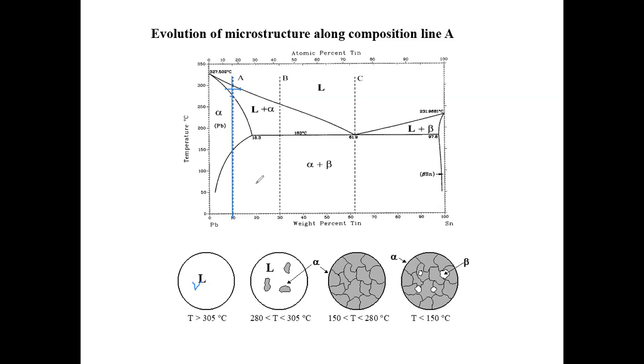So you have this alpha phase, but if you further cool, you're going to get into this precipitation growth, okay? But in our classes, for now, we're only talking about solidification, so we're not interested in these two stages. We're only interested in this particular stage, where starting from a liquid, you cool the system, you get into a two-phase coexistence, and then you keep on lowering temperature and you complete the solidification.